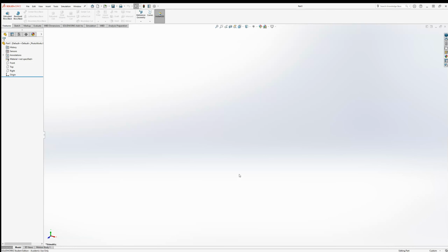And so if I switch back over to SolidWorks, one way you can see it is down here in the very bottom right. I'll see where it says custom, and I can actually click that, and you can see I've got a bunch of different unit systems here. And so MKS, where the length measurement is meters, the mass measurement is kilograms, and the time measurement is second. CGS, MMGS, and what we're interested in here in this case is IPS, inch, pound, second. So I'll click it, and so now all my length units will be measured with inches.